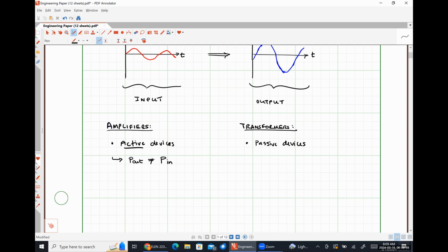Have any of you ever heard the term power amplifier before? None of you work on fixing your car stereo or play guitar or anything like that? Power amplifiers provide extra power to drive a large load like a speaker, right? A speaker is going to convert some voltage signal into sound, but because the speaker has a lot of physical mass, it requires a power amplifier in order to drive that cone and cause it to generate pressure waves, which we interpret as sound, right?